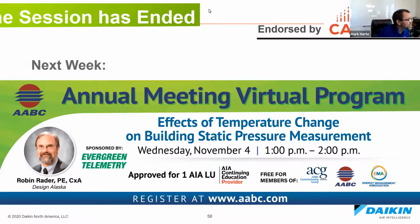We have BACnet and LonWorks to interface. There's probably more control features. I know there's some Modbus stuff going on now, but I'm not into that. If you have questions on that, I would look on Daikin City and go under controls and see what's coming out. I think there are some adapter PCBs, but if you're just talking about gateways, we have BACnet and LON, and we can interface with most control front end systems that I know of. Okay.